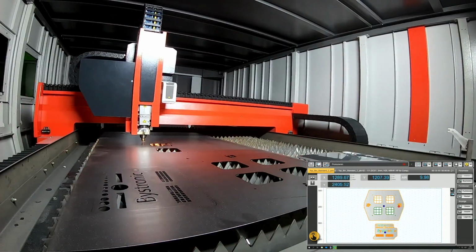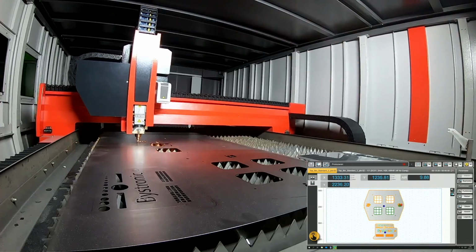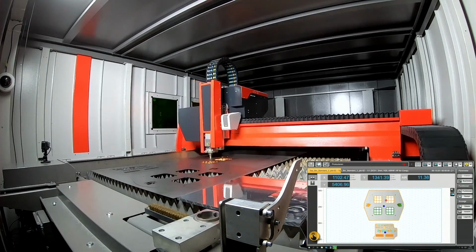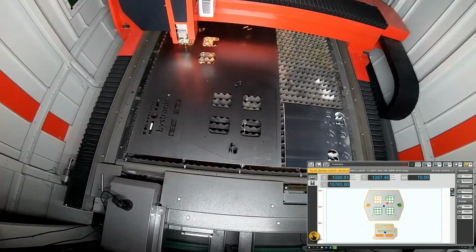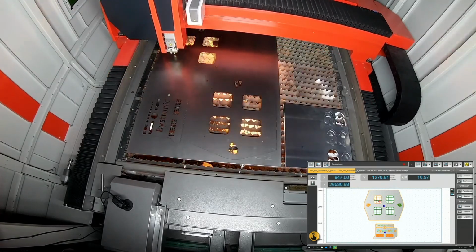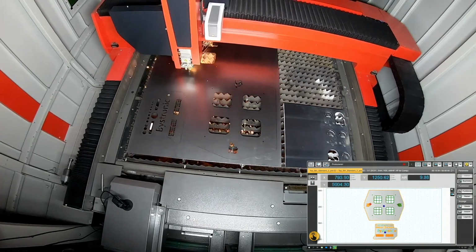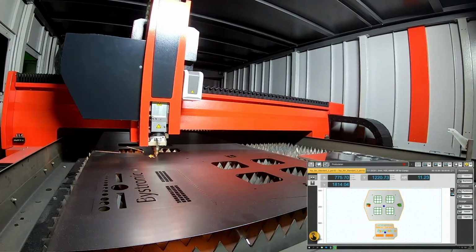At the moment, what you can see is some separation cuts on the small contours and as well on the big contours. The idea of that is that we can avoid collisions and micro joints. What you don't want to do is to have micro joints because they will leave marks, and you don't want your parts to flip over either. So that's why we separate this. Our software is doing this, of course, completely automatically.